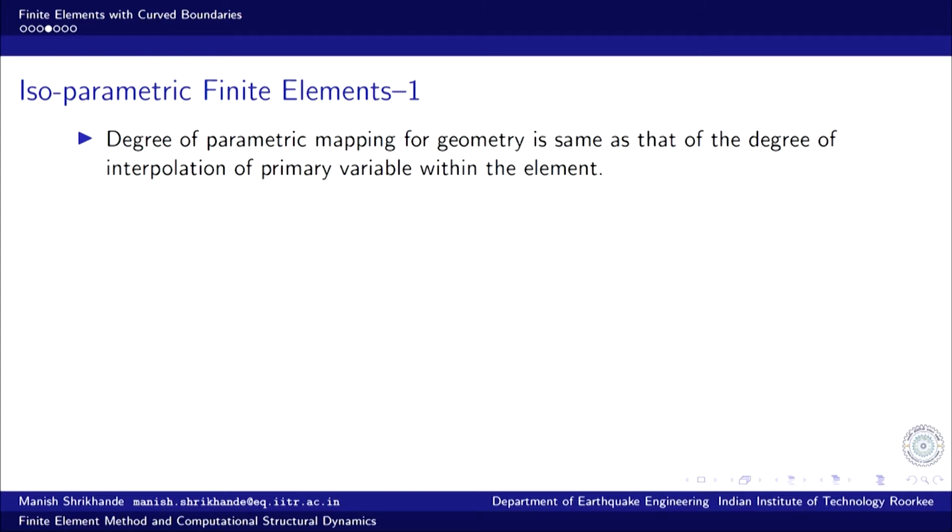So, we use isoparametric formulation in our subsequent discussion. We will not refer to subparametric, because as I said earlier, it is a subset of isoparametric formulation. Superparametric is generally not used in the context of finite element analysis. There is not such a need for such a high degree variation of geometry.